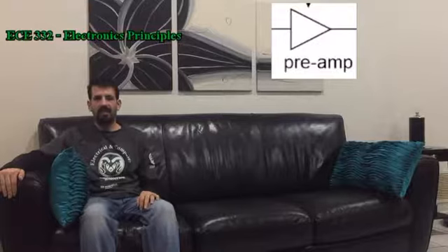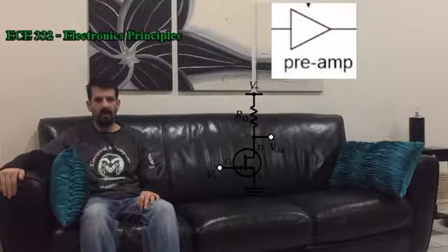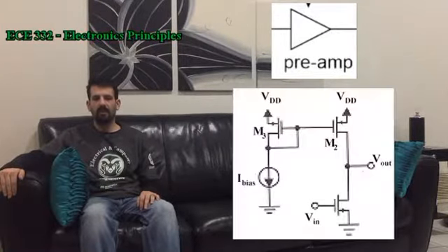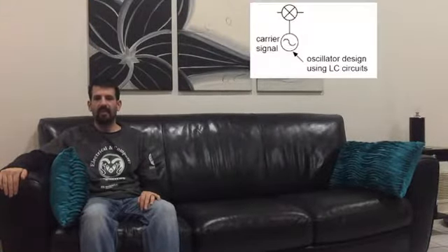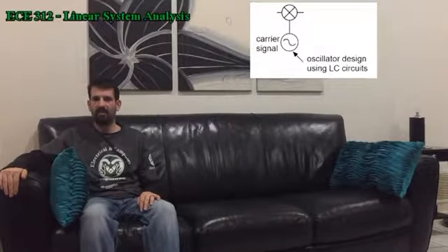From ECE 332, the preamp stage boosts the baseband input signal, conditions the output to have the correct DC bias for the next stage, and filters out any noise from the amplifier. A simple preamp can be built using a single common source amplifier with a single CMOS chip. A better but more costly preamplifier can be built using a current mirror which sets the bias for a common source amplifier.